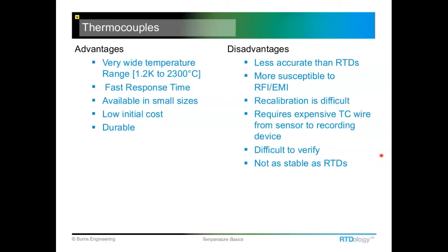There's really not a good way that you can take a thermocouple and pull it out of your pipeline or tank and go take it to a lab and measure it and then bring it back and have it actually perform the same as what you just measured in the lab. The best way to do it is to measure it right in that spot, where you may just pull the thermocouple out and put it in a bath of known temperature and read what it's telling you.